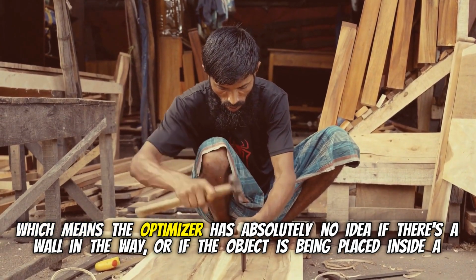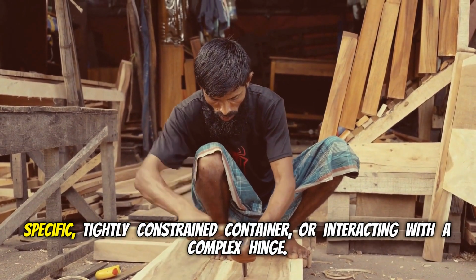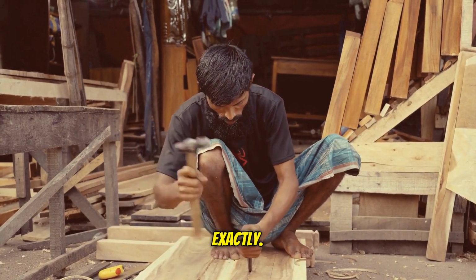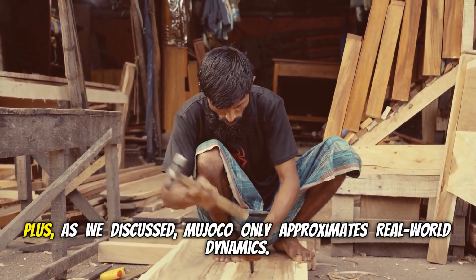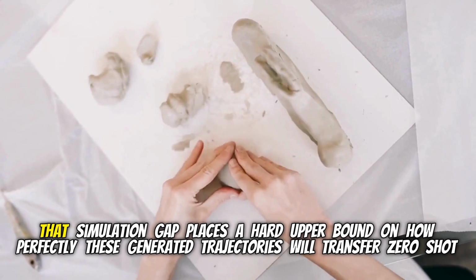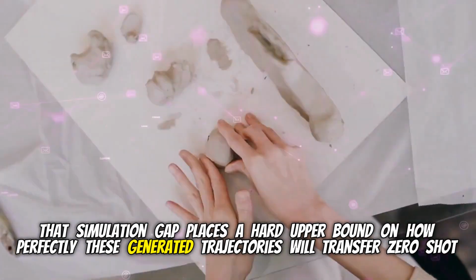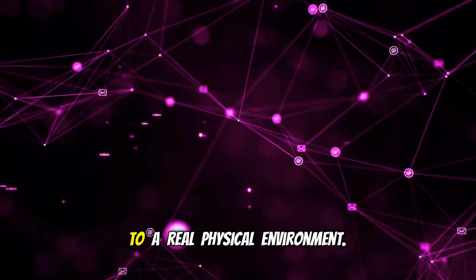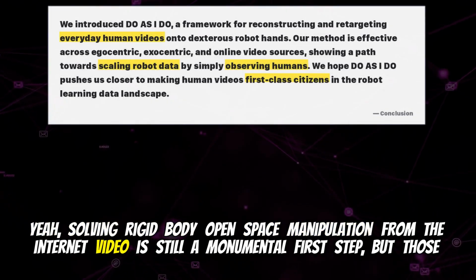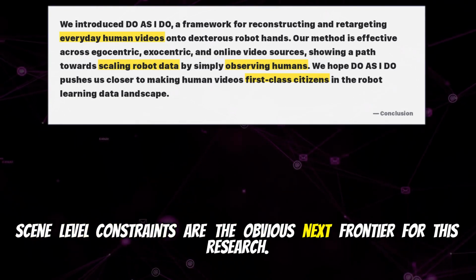Which means the optimizer has absolutely no idea if there's a wall in the way, or if the object is being placed inside a specific, tightly constrained container, or interacting with a complex hinge. Exactly. It lacks all environmental constraints. Plus, as we discussed, MuJoCo only approximates real-world dynamics. That simulation gap places a hard upper bound on how perfectly these generated trajectories will transfer zero shot to a real physical environment. Yeah. Solving rigid body open space manipulation from internet video is still a monumental first step, but those scene level constraints are the obvious next frontier for this research.